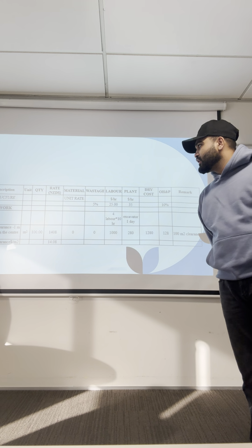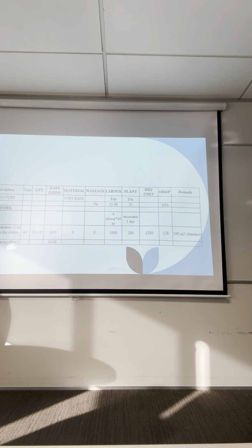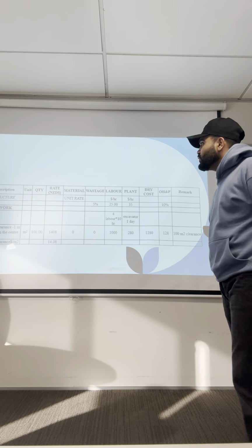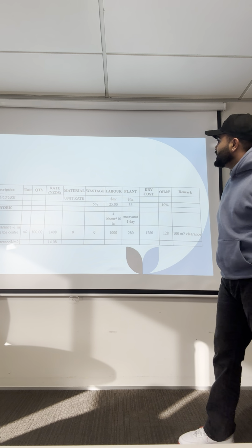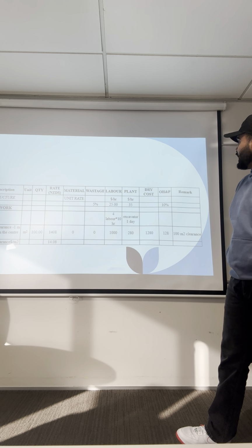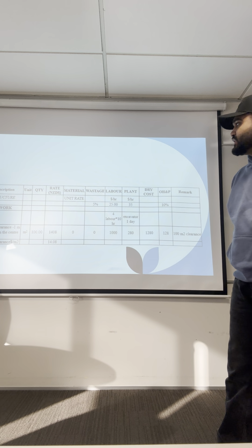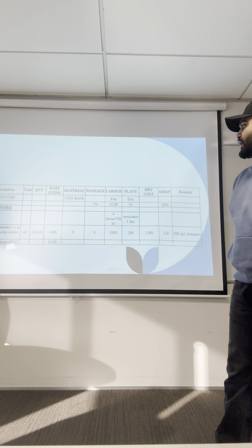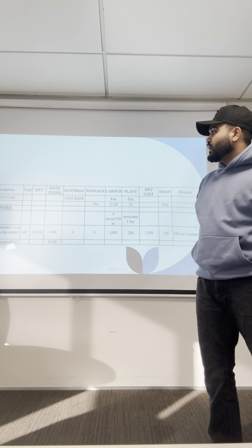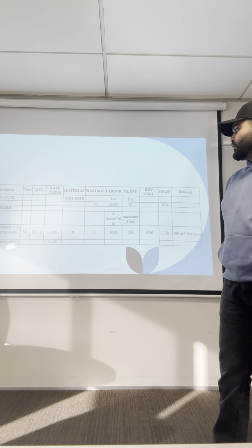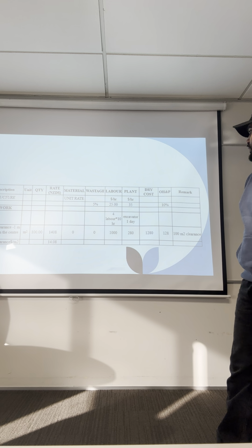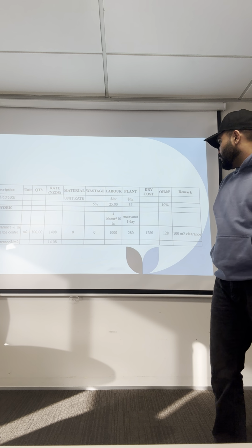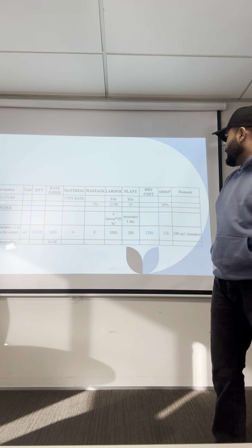These are some codes, like earthwork. For earthwork, the pay rate for 1 hour is 25, for plant it is 35, and overhead and profit is 10%. Ground clearance is 1 meter length from the center line, in meter cube, and the quantity is 100. In New Zealand dollars, it is $100. The labor cost is 1000, and plant is 280. Direct cost is 1280, and overhead and profit is 128.